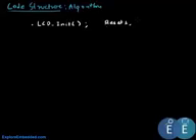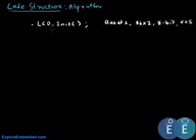Then it sets the function: it sets it basically as a 16 cross 2 display, it sets the data bus length as 8 bit, and then it selects the font size as 5 cross 8 as default. Now all this is done in the lcd init command.